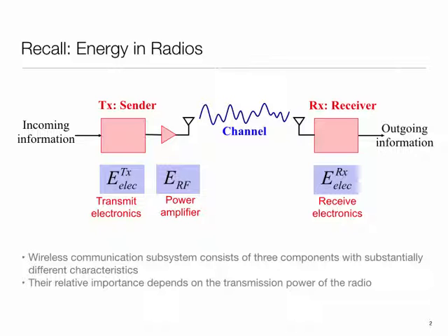All these things like capacity of a channel fundamentally boil down to the fact that your signal to noise ratio affects the capacity of the channel, namely the rate at which you're going to be able to send information. Therefore, if you have more time, you can send at a slower rate, and accordingly you would need less energy per bit. There are very magical numbers. If you do a communication class, they call it Eb over N naught. N naught is the noise, Eb is the energy per bit, and basically if you are communicating slowly, then you need on a per bit basis a lower amount of energy, not power, energy is lower.